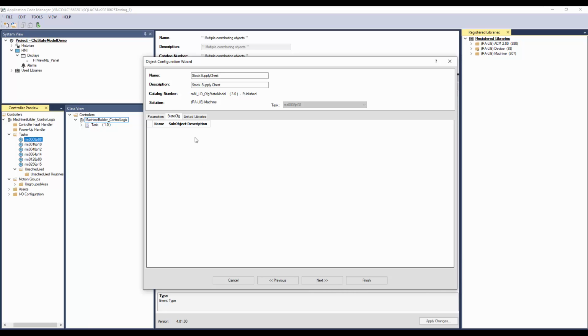To add a state, right-click and click Add New. Enter the state name. I'll enter as resetting. Enter a state number. Enter the button label. If no command button is required, then leave it as no command. Enter the next state number. If resume enable is desired, then select resume enable. Select the transition condition for the states.